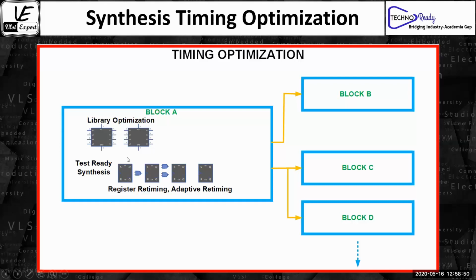Next comes test-ready synthesis. For this, we'll explain what exactly test means. Here, we will be focusing primarily on DFT using scan. We'll give you an example of scan chain insertion, which is the most common DFT in the industry. Pretty much everyone does at least scan-based DFT. We will tell you how a synthesis tool optimizes your scan insertion, how it takes timing into account, and by pre-analyzing the scan flops and other things. Okay.